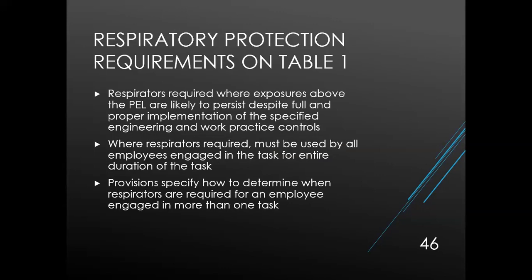If exposures are above the PEL despite the full implementation of the specified engineering and work practice controls, those employees would be required to wear respiratory protection, and all employees engaged in that task must wear that protection for the entire duration of the task.